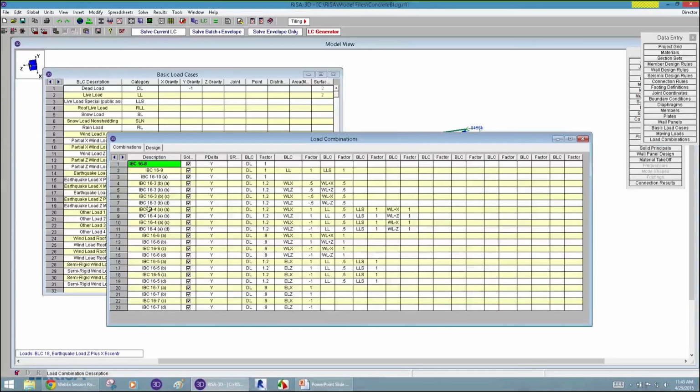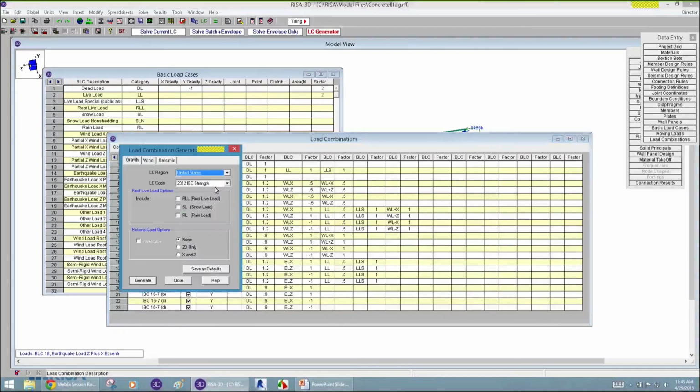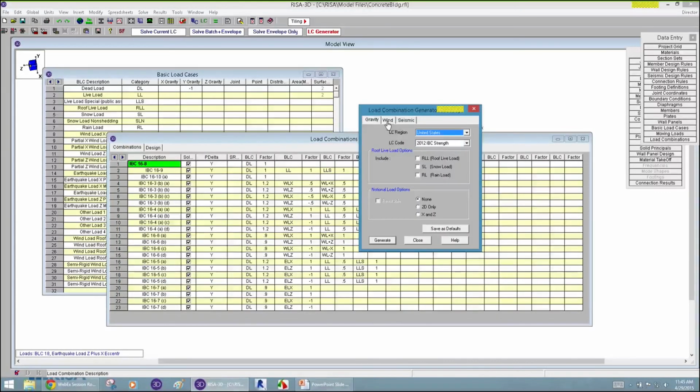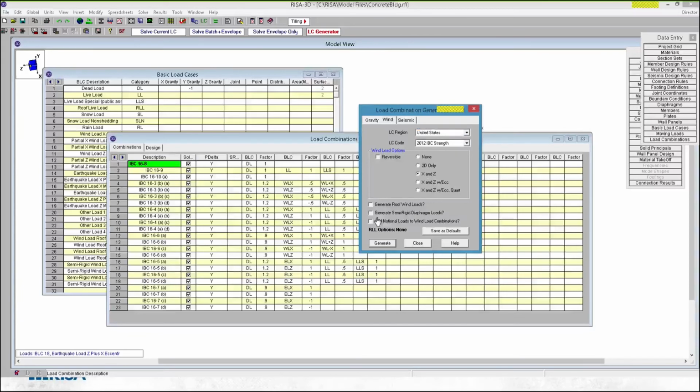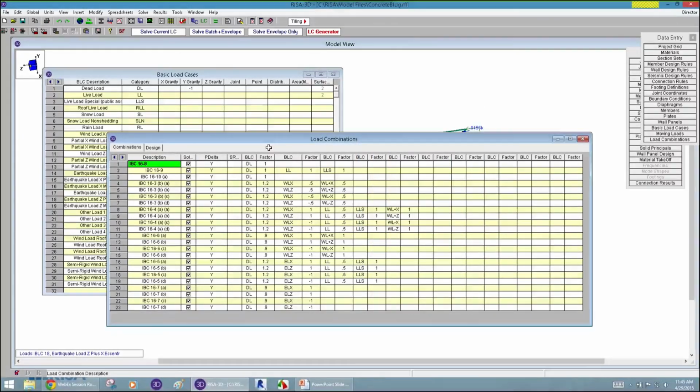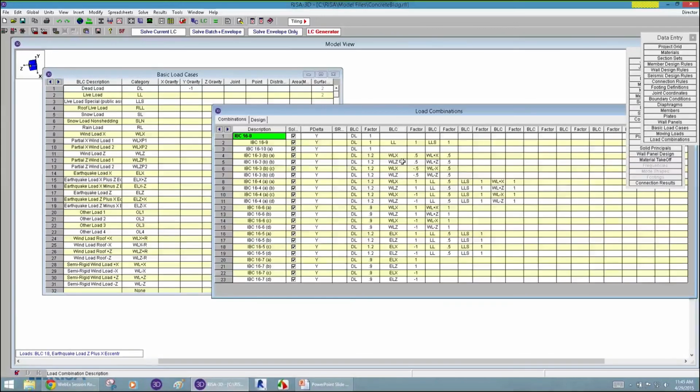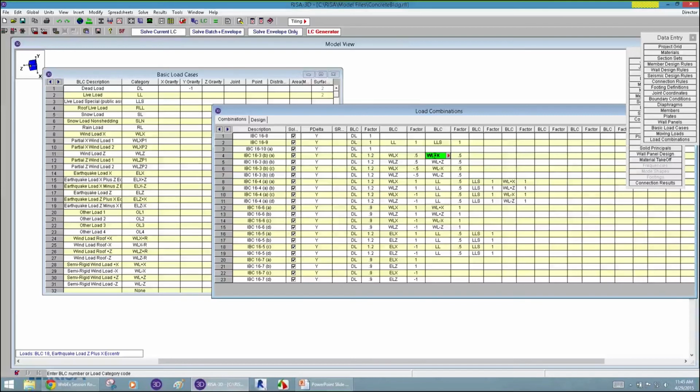And I see that we already have here my different load combinations. If you forgot from the last one, all we did here is I used the wind, X and Z using that semi-rigid diaphragm. That turned on, and it is important just to point that out again. This is probably one of the biggest user mistakes is the category there, WL plus X. That shows this WL plus X right here is that semi-rigid. Those are the values that are going to be applied.